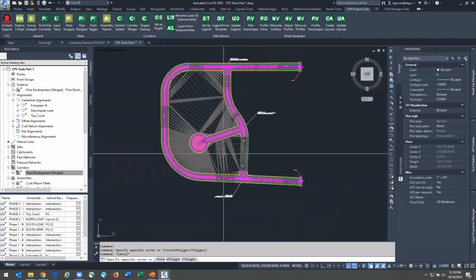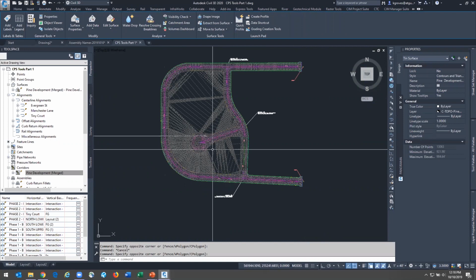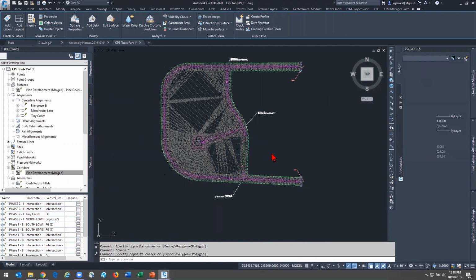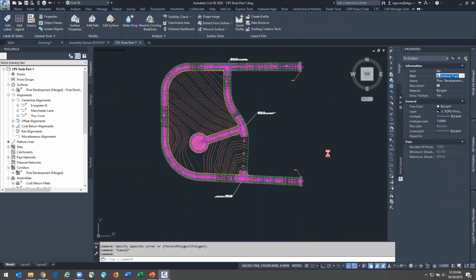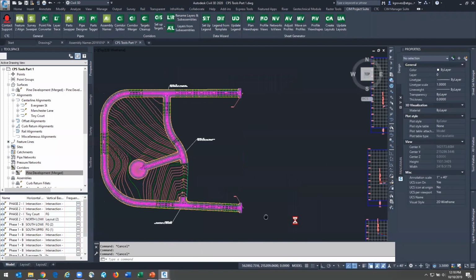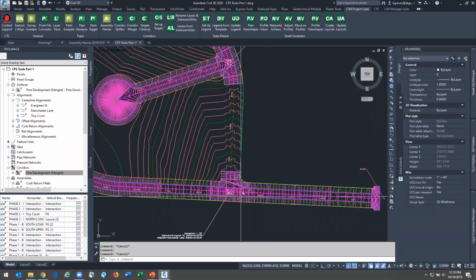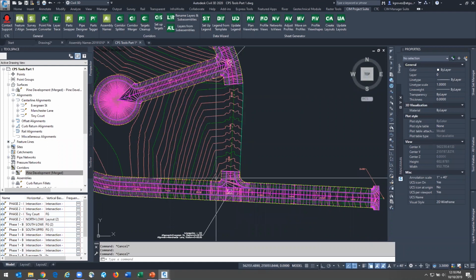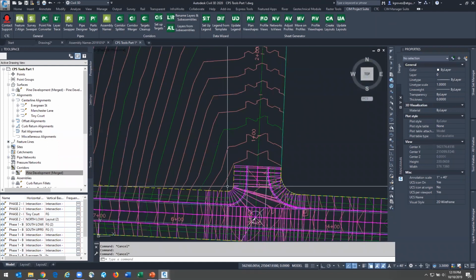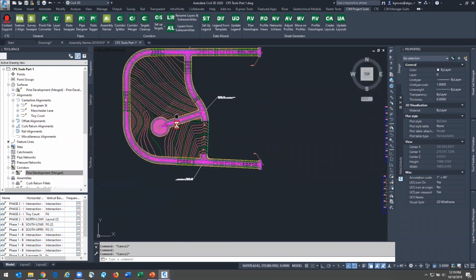We're not going to get into that today, but no, your corridors, Adam, do not have to be touching in order to merge them, because corridors by themselves don't require that workflow. So this tool isn't doing anything new. We're not doing anything that the software couldn't do already as far as modeling the corridors and such is concerned. It's simply a way to make sure that you can break them apart and put them back together. That is obviously an add-on, but the corridor toolset is still functioning purely as designed, as intended.